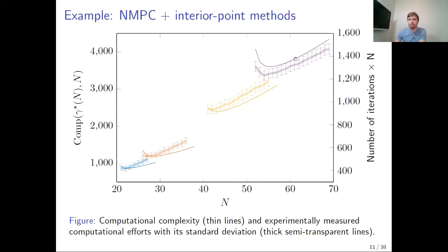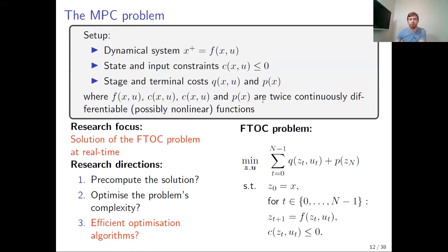As you can see, it provides a nice insight on the fact that you should not choose the smallest stabilizing prediction horizon length. You can increase it just a bit, so you can add more suboptimality in your solution, and in this way you will decrease the computational complexity of the overall problem. That's it for the previous contributions.